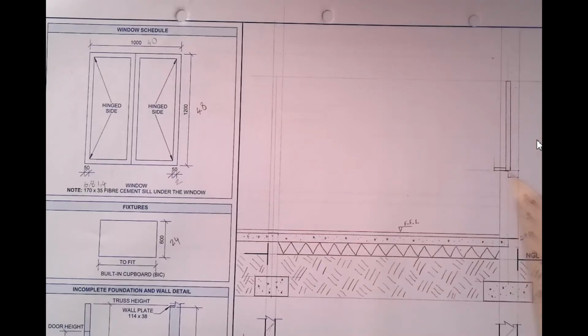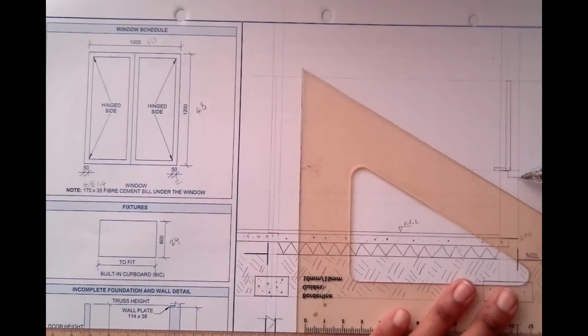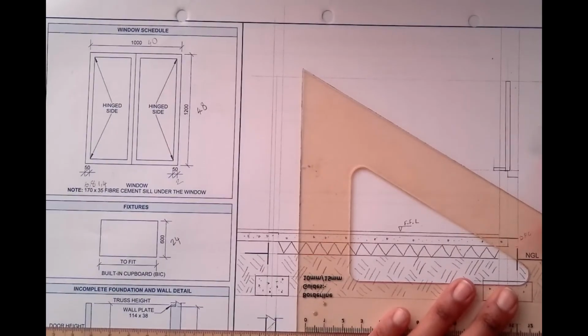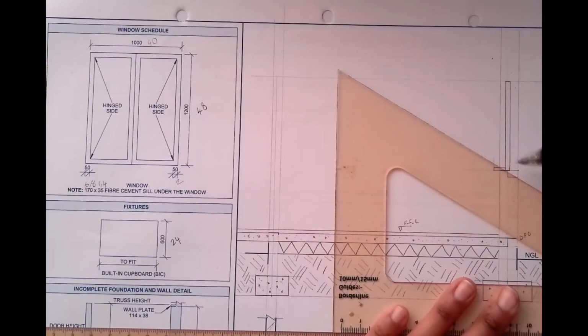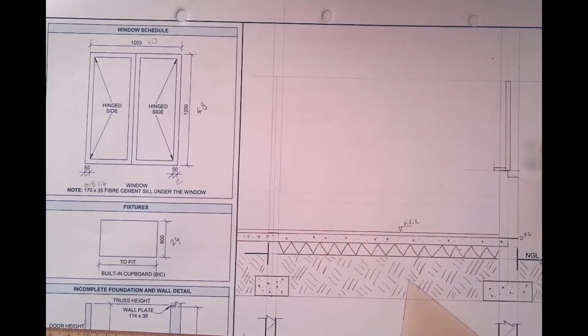And then I have to do the same for the one that is slanted on the outside. For that, I'm going to use my 30-degree set square, and I'm going to draw a line at 30 degrees that's going to touch this corner here. Just a random line at 30 degrees. There. And then again, I'm going to draw a line from this corner of this window at 30 degrees.